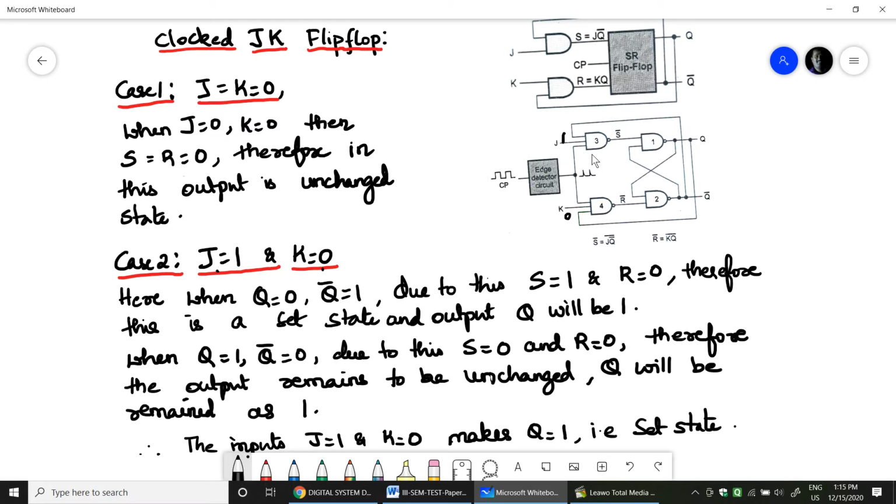So with this, when the clock pulse is applied, both of these will be 1 1, and now if we assume Q to be equal to 0, and this 0 is given back to this, and it is given here also, therefore 1 0 0. So if any one input of a NAND gate is 0, the output of the NAND gate will be equal to 1,